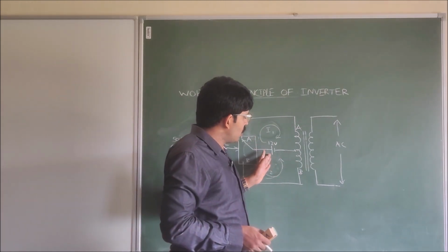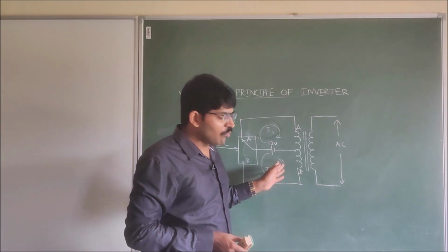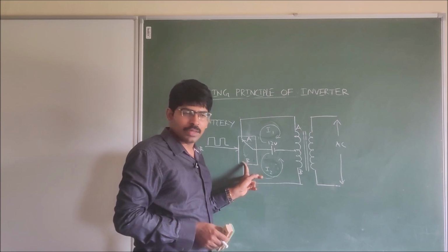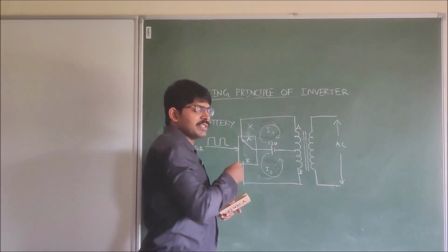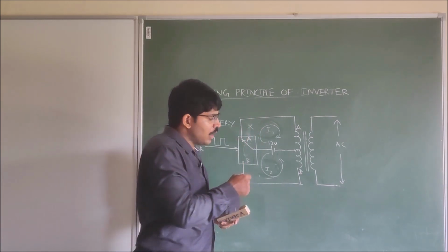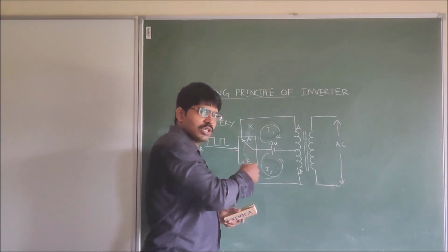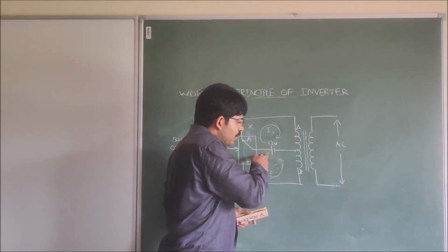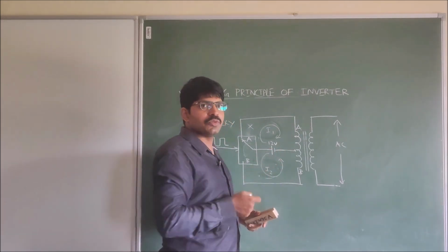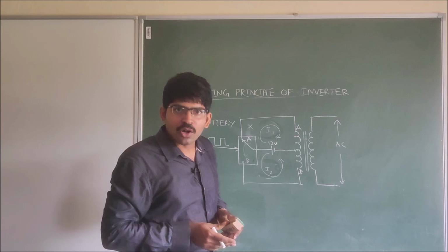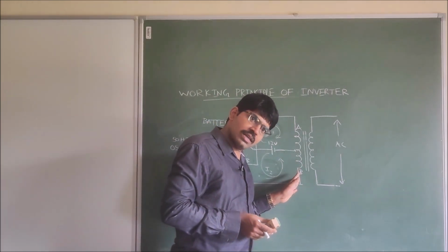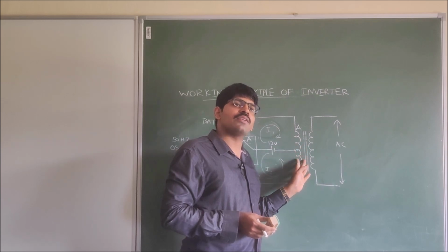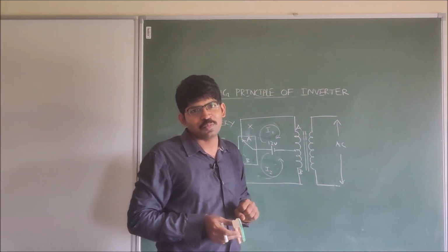Now, similarly, when we are connecting from point A to point B, there is no current in the upper circuit. Now the current flows in the lower circuit in the opposite direction, because we always represent current as starting from the positive terminal of the battery. Again, because of this current, a magnetic field is generated and this magnetic field is stored in the inductor.